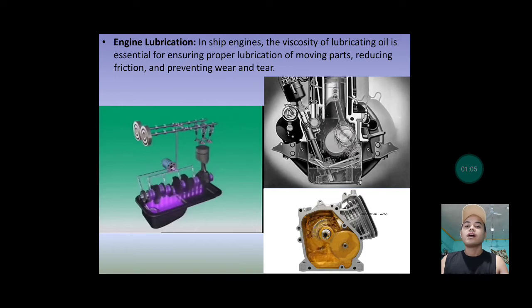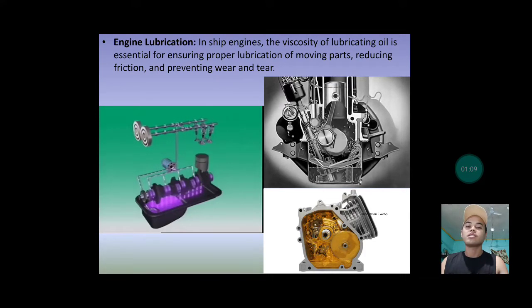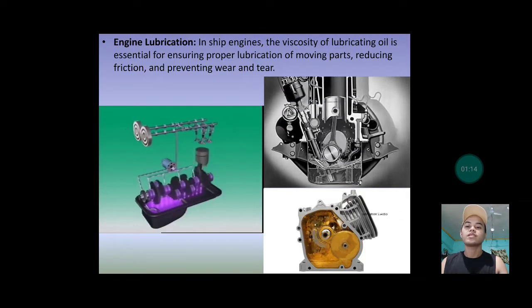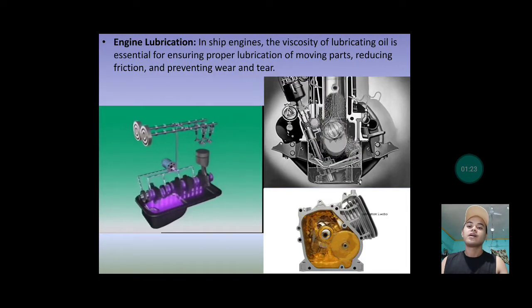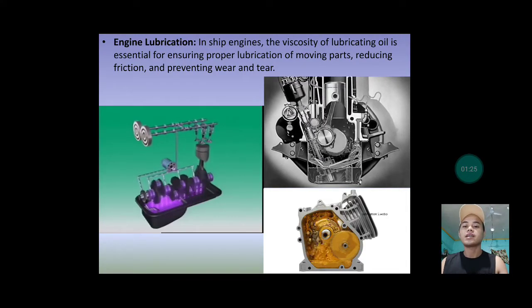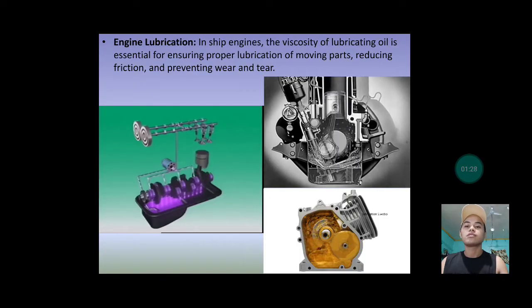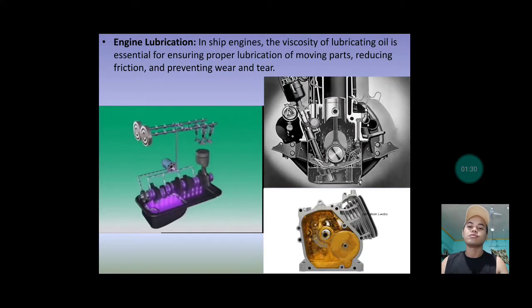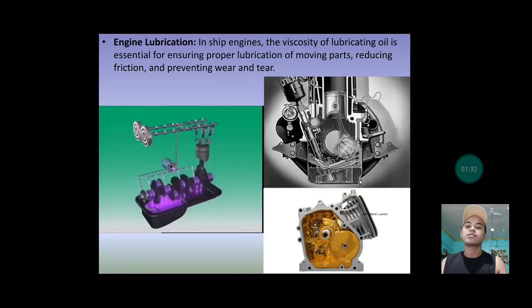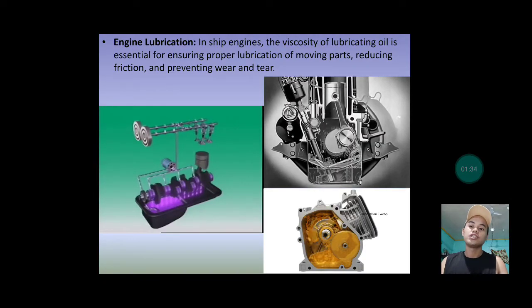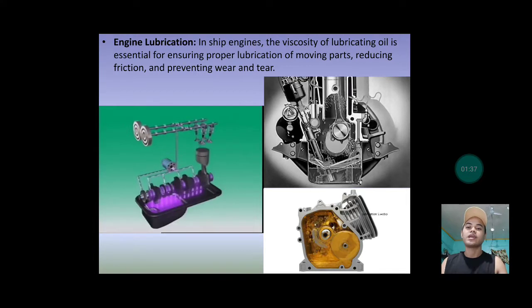If your engine has a lubricant that is low in viscosity, or mas malabnaw, then the protection from friction, from noise, and from metal to metal contact goes down. So the more damage it will get, the more damage for the moving parts of the engine.